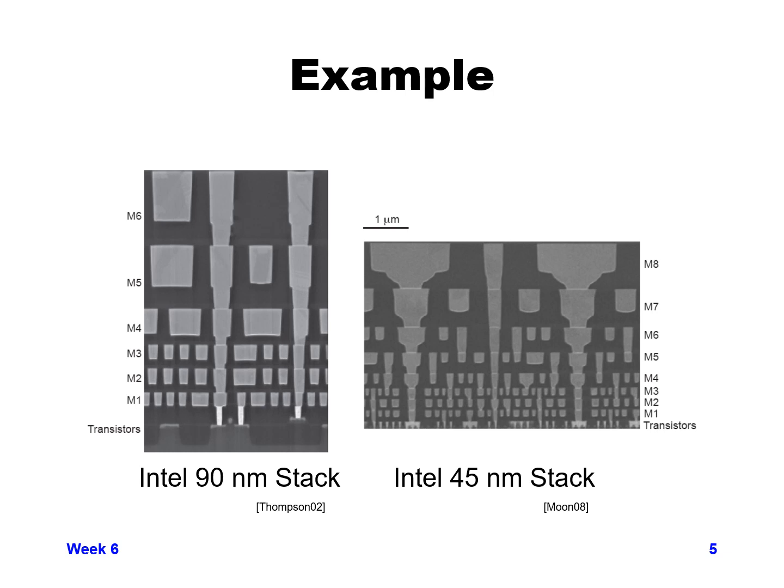As you go from metal 1 up to metal 6, you can see the width of the minimum width metal 6 is much wider than the minimum width metal 1 by probably a factor of 4 or 5. Kind of hard to tell exactly here. But then going to the 45 nanometer where they went up to 8 metal layers, you can see the minimum metal 8 is definitely a lot wider than the minimum metal 1 down at the bottom.